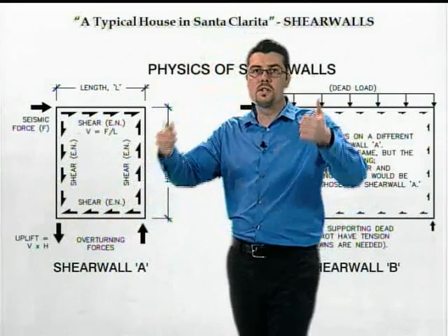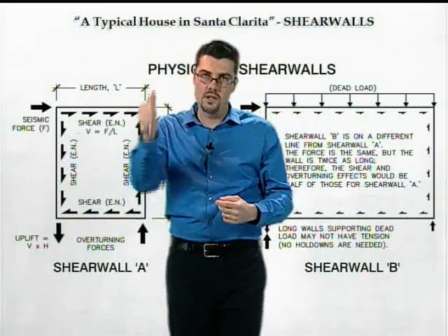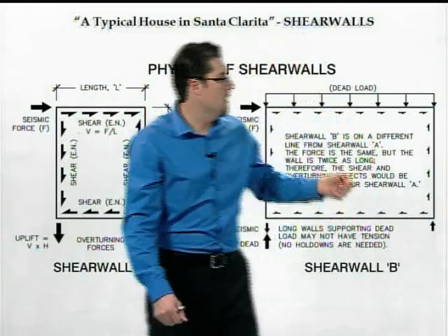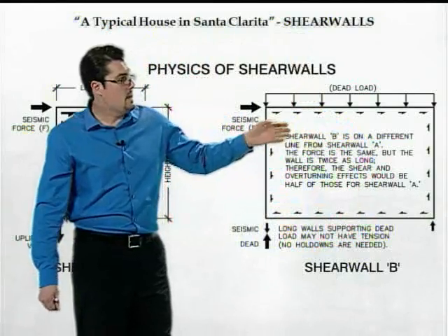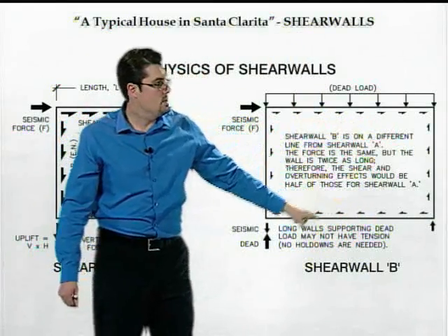Those overturning forces have to be resisted by either straps or hold downs, which we're going to see when we get into the actual design of our house. Now, as the shear wall gets longer, those forces diminish.